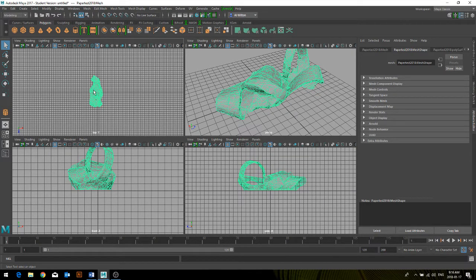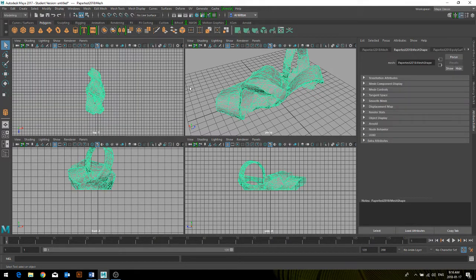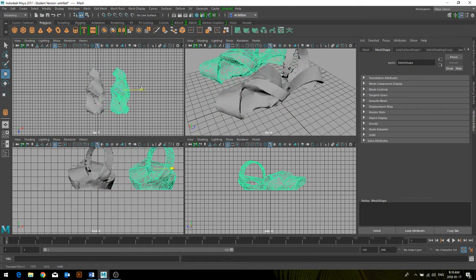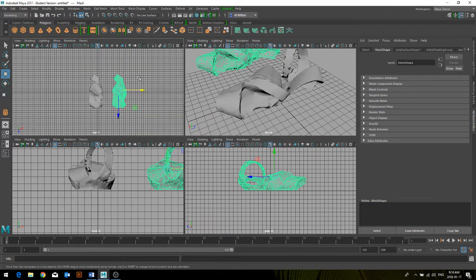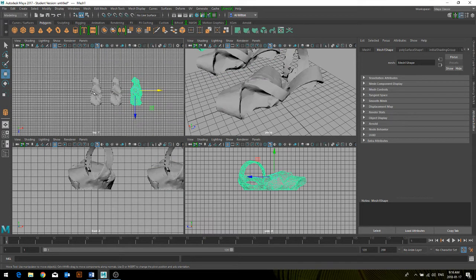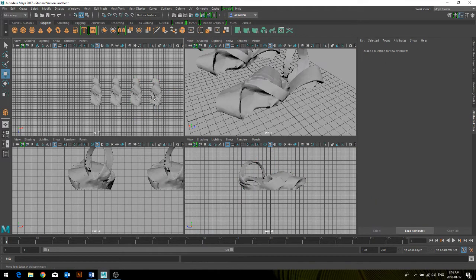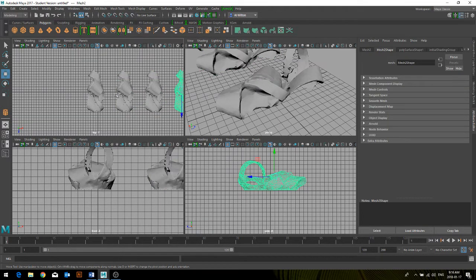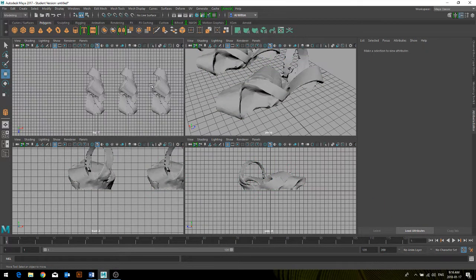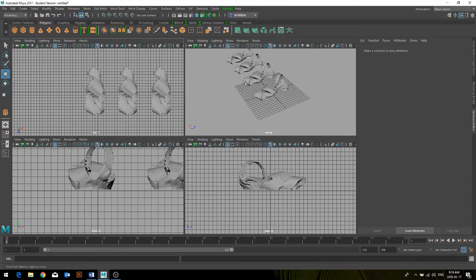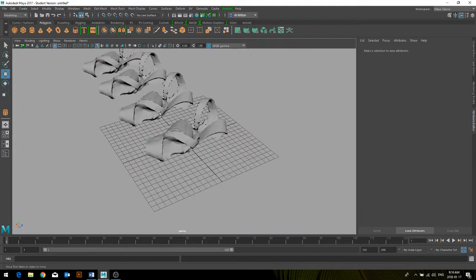So once you have the model and the one that you want to manipulate, you can go into your top view or your perspective. Really, it doesn't matter which one. But if you click Control D, that's the quickest way to create a copy of the geometry that you have. And then if you click Shift D, you repeat the command as well as the distance, so you can create that network of geometries that you can then go in and manipulate. And so I have a few geometries to play around with today. I'll just go into my perspective.